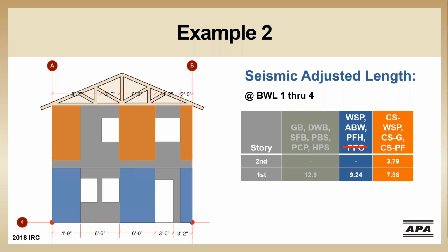If you recall the irregularity check we did earlier, braced wall panels above can overhang the opening by up to a foot without issue. We theoretically could use even more of the length with the right header, but as it is, we have plenty of length, so it's really not necessary. You might also think, hey, I have way more wall length at the top floor than I need. Can I reduce it? And again, the answer is yes. Probably not in reality by very much.